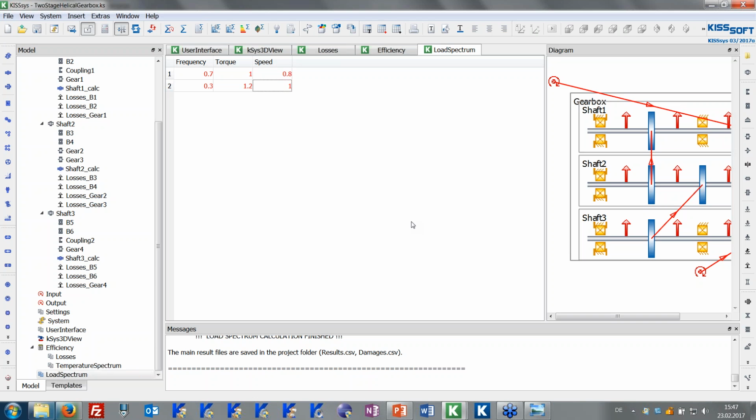Second question, how would you approach more complex housing models which are not rectangular or cylinders? Do you just use CAD to calculate surface area and give an overall length, width, and height? And that's exactly the case. So you can simply enter the total surface area for your housing to calculate the heat dissipation. The shape is only used for the churning losses of the gears, but can be approximated.